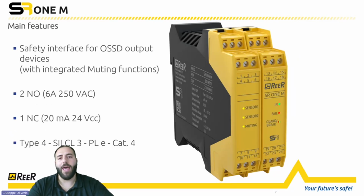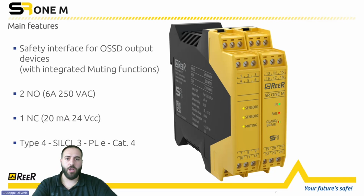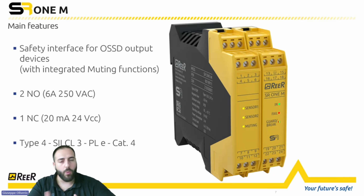The SR1M is basically the same as the SR1 plus the muting integrated function. So in order to do a muting logic with two sensors across a beam, for example, that is one of the most common muting logic, then the SR1M is the right solution. Of course, again, you have to connect the light curtain, sensor, and interface.